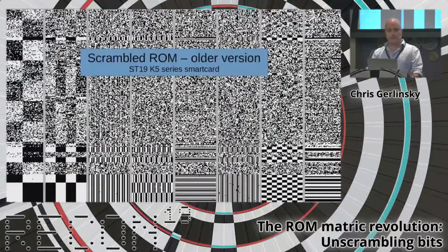So one of the pictures isn't showing up here, unfortunately, for technical issues. If we look at the decrypted version of this ROM, then all the areas with the really black and white checkerboard patterns actually did decrypt perfectly to 0. Those were just empty spaces, and then we have code in the rest of the space. So being able to visually see these patterns is the whole basis of how I'm descrambling these ROMs.